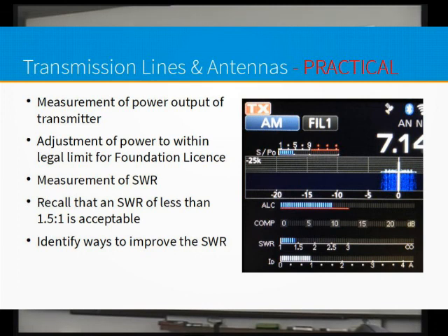I'll tell you up front, we're going to be transmitting between this room and that room, so if it's nothing less than 5 and 9, I'll be a bit concerned. What's the ID? It's current, what the transmitter's drawing. It's down the bottom, that's 1 amp basically. So it's drawing 1 amp when it's transmitting at that particular point in time.